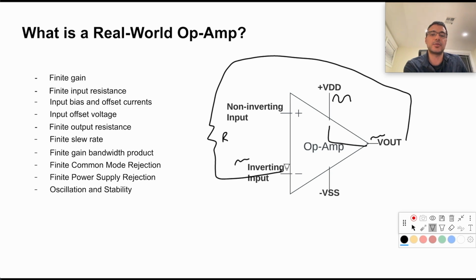And then that is going to be amplified. Again, the output will become larger and it will go back and create this positive feedback loop, which eventually might cause the op amp to oscillate, which is undesirable behavior in most circumstances. It might make it unstable.